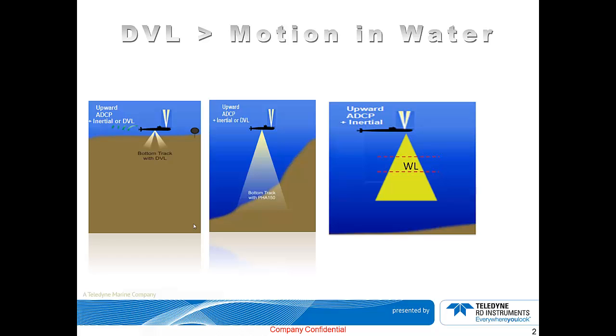There are two basic commands or parameters to keep in mind when water tracking. These are BL and BK. The BL command basically sets a water mass layer. You can use this layer as a reference point when the bottom is out of range or is incorrect. There are also various guidelines to note when setting a water layer.